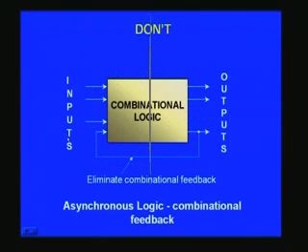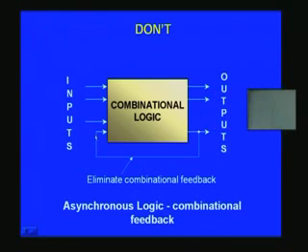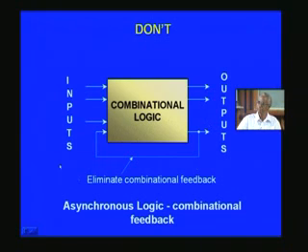And it basically consists of do's and don'ts, because this is supposed to be a guideline as such for the designers. And the common mistake that we make is to take a combinational output and feed it back, and this is detrimental in making a chip as such, because for example, if you apply a 0 at the input here, and the combinational logic might produce a 1 here, and then 1 being fed back, it keeps on rapidly switching from one state to another, and this will be uncontrollable as such, and thereby it will not work in the ultimate chip that you have designed. And furthermore, this may be rejected at the synthesis level itself.